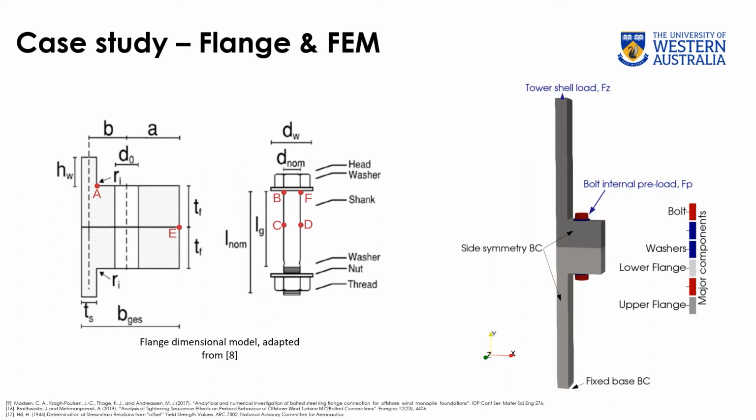The flange face material is assumed to be S355 ML structural steel. 6 locations of interest are assessed, locations A to F. GP surrogate models are built to predict the stress field at each location. The flange arrangement is modelled in the SimScale FEM package as a static, nonlinear simulation of the segment model of the maximally loaded segment with a simplified bolt nut geometry.